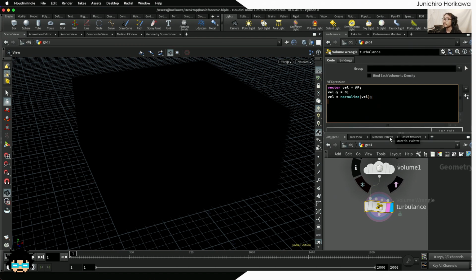Okay, now I'm going to set the y value again to make it a bit more jittered, so that you have some randomness on the y direction. Okay, so for that I'm going to use the noise function based on the p and some scale value like 0.01, could be any value, and then the value you get is in between 0 to 1, so you might want to have a negative direction going downward as well, so I'm going to subtract by 0.5. Now I am going to multiply this back with a bit higher value like 5.